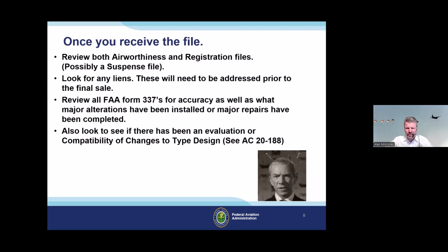That was a recommendation by the NTSB because there was an aircraft that had several alterations done to its wing. I think there were two or three alterations. Each alteration changed, I don't remember if it was stall speed, but let's just say stall speed. So if you have three wing alterations, all with approved data in and of themselves, installed on this aircraft, each time, when the first one went on, there should have been an evaluation to see that that install didn't affect anything else or a previous install. And subsequently, the same thing should have happened for the second install and the third install.